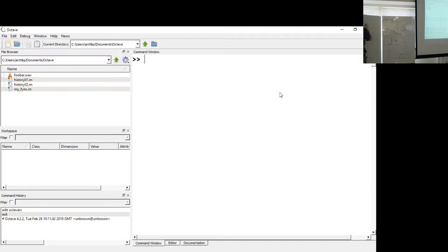Then I would put here on this angle a zero and a pair for it. By the way, in order to get real values for the system coefficients, the zeros and poles must be complex conjugate pairs or on the real axis.